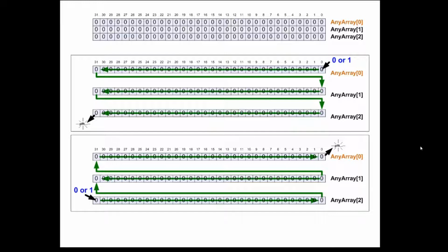A bit shift instruction is going to shift the value from one bit to the next bit, whether it's to the left or to the right. As you can see here in the top illustration, and remember what I told you in the manual, when it comes to the bit shift left and bit shift right, left and right has nothing to do with your left and right. Now, on the screen here, it just so works out that it is your left and your right. Don't depend on that, especially in your logic. Don't be thinking your left and right, or left and right on the screen.